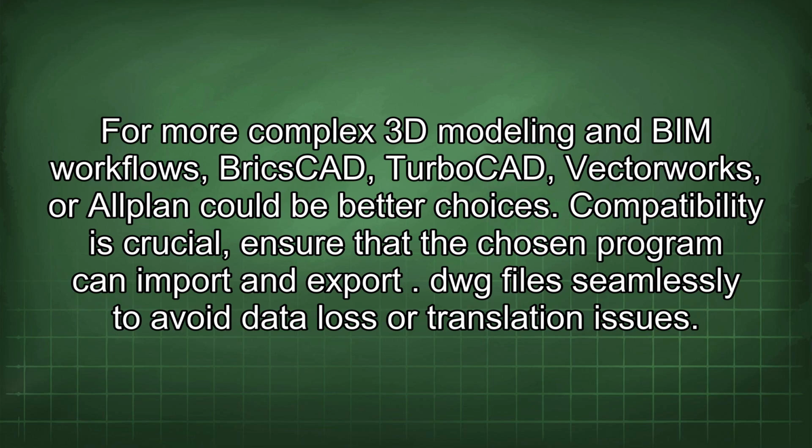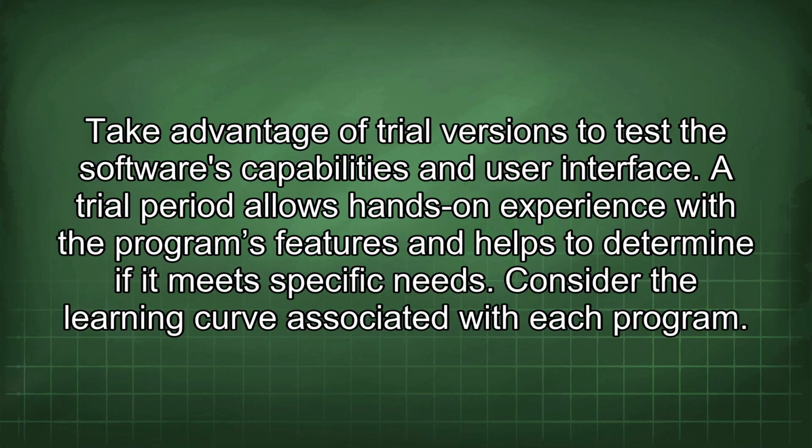Compatibility is crucial. Ensure that the chosen program can import and export DWG files seamlessly to avoid data loss or translation issues. Take advantage of trial versions to test the software's capabilities and user interface. A trial period allows hands-on experience with the program's features and helps to determine if it meets specific needs.